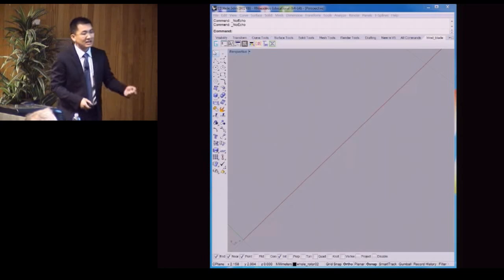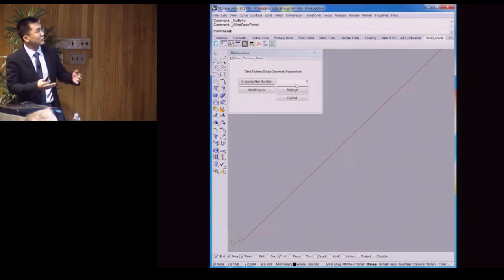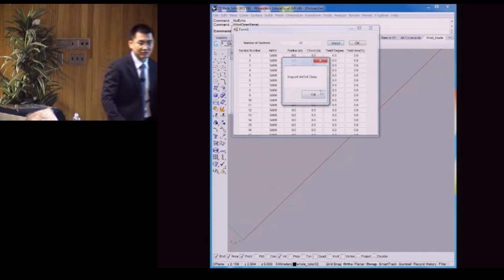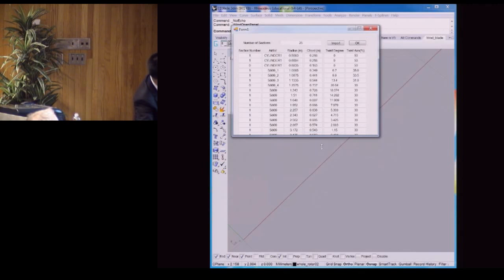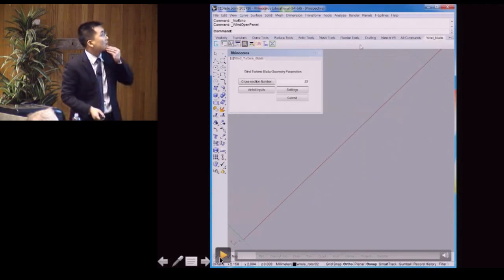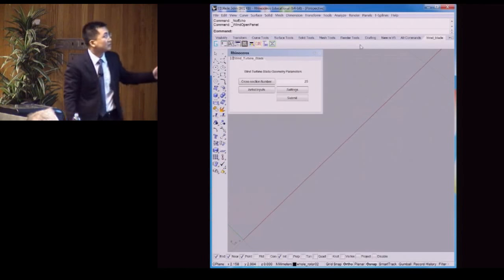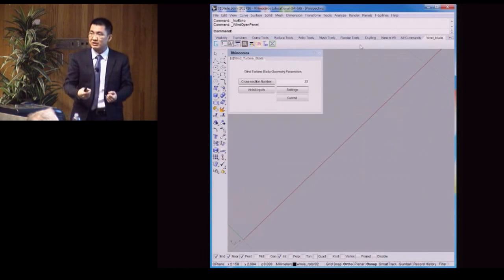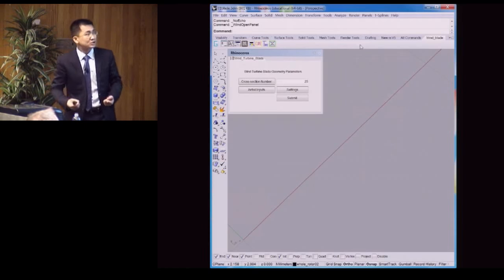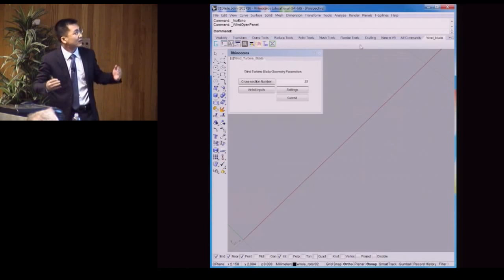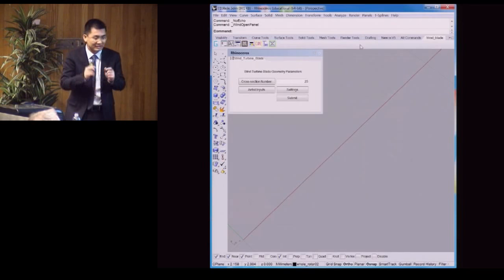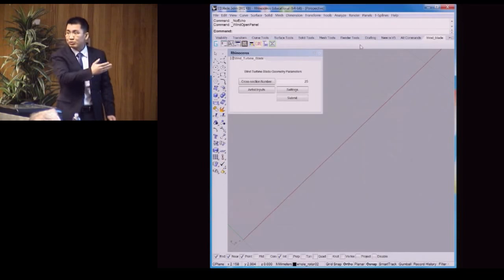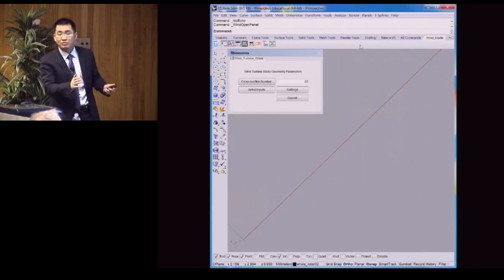Using the idea of isogeometric analysis, we can develop a framework under a software called Rhino. What you see here is we pick a computer-aided design tool called Rhino. The reason we pick it is it allows a lot of flexibility to program plugins. So you can have crazy ideas and then program them all under this software. Functions like non-uniform rational B-splines are already provided. You don't need to write your own code for this.